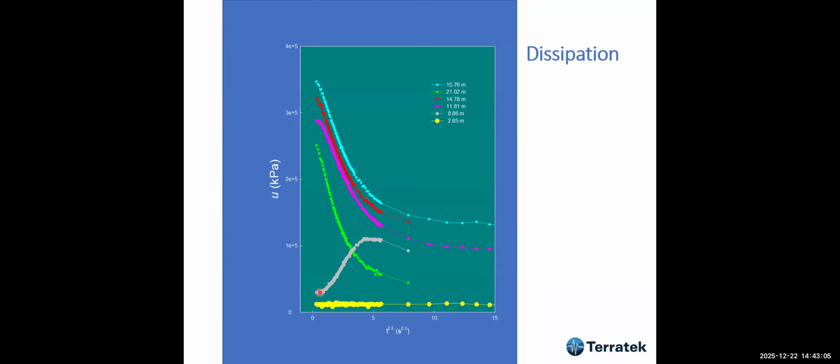And also, if we go into an over-consolidated soil, the dissipation can be in the other direction. I mean, in over-consolidated, very hard soil, the delta U is going to be negative. So when we stop, pore pressure goes up to the hydrostatic situation, and that's what happens.